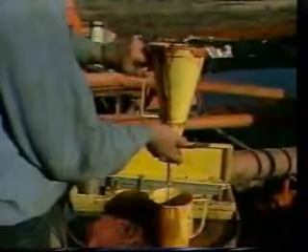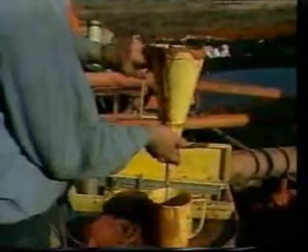The viscosity of the drilling mud, being measured here with a Marsh funnel, is the property which helps it carry cuttings up and out of the hole as it is pumped through the circulation system. A drilling fluid must have gel strength to hold the cuttings in suspension should pumping stop, and yet must quickly liquefy when pumping begins again. Cooling the bit is also an important function, especially considering the heat which can be generated by the forces applied to the rapidly spinning bit, and the subsurface temperatures which increase with depth.